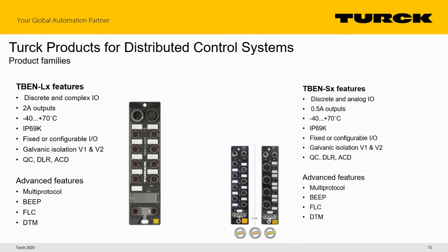I do want to dive into the TBN-L product a little bit to give you an idea of why block I/O works in so many applications. So our TBN-L block, if we have discrete I/O points, is 16 discrete I/O points. We have up to 2 amps per output.